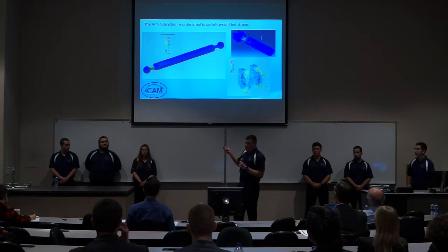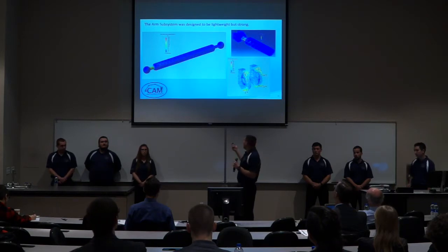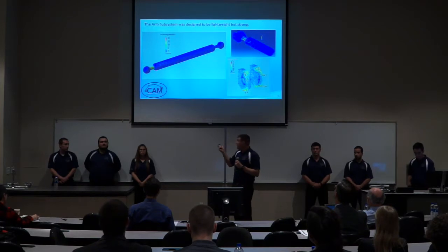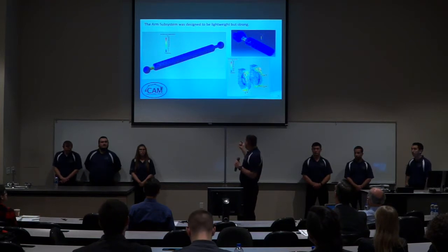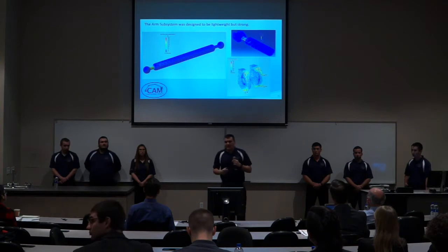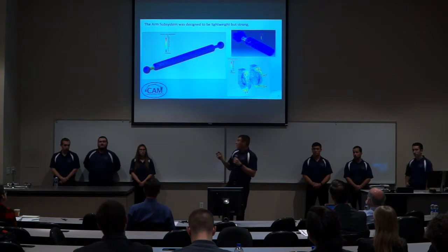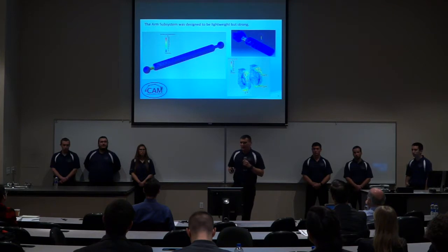You can see the stress concentration building up at the stem of the ball joint. Similarly, you can see that on this test, which included the plates. And then on this test, we did a 20-pound force at a 45-degree angle from the plates to simulate the ball being forced through the plates. In all of these tests, the maximum yield stress we saw was 11% of the total yield stress of aluminum 6061. So we're nowhere close to bending or breaking any of our components, which is good news.